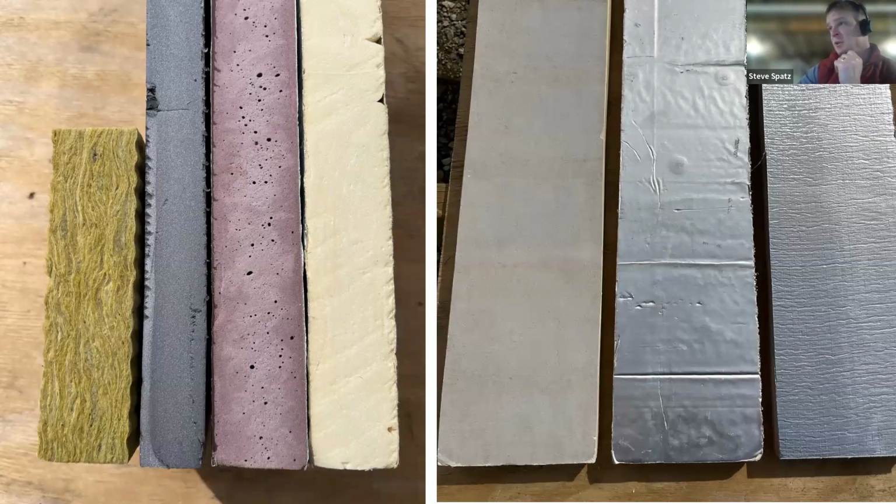Breaking this down even further, now here's 3 different options of essentially the same insulation type. So these are phenolic foam boards, but with 3 different types of facing on them. So the facing on the material also has an impact on vapor transport, its capacity within the assembly as well. So I can't get into all of the details of why one versus the other in the context of the time we have here today.